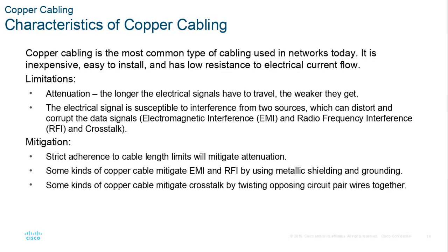Instead of the old 277 volt fluorescent fixtures with ballasts that emitted a bunch of electromagnetic interference, they replaced these with LED panels. They don't have transformers, don't emit radio frequency, and don't emanate electromagnetic interference.